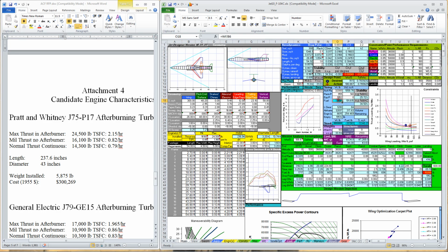Oh yes, it did. It saved some weight on the wing, a couple hundred pounds, and it actually sort of helped us fly that combat turn a little bit better too. Now the only way to really fix that combat turn is to make the wing bigger, I think. You can see on the constraint diagram that the plus is over to the right of the circle, and that tells us that our wing is too small. Let's try 350.